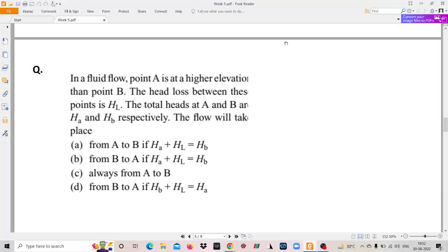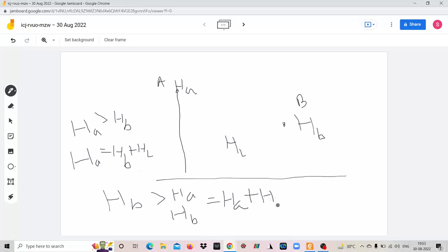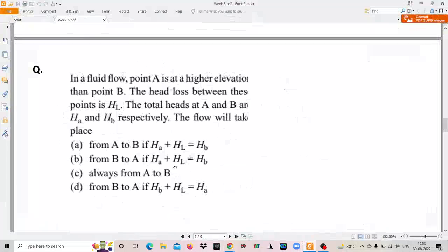Yes, sir. B to A. Now, if the flow has to take place from B to A, then HB should be greater than HA, or HB should be equal to HA plus HL. So, HB is equal to HA plus HL, right? So, the correct option is...